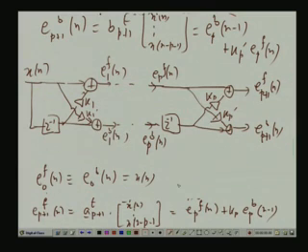This is called a lattice filter. This is one of the most celebrated things in statistical signal processing. This is used for AR modeling and particularly used in the speech context, because our speech generation mechanism in our vocal cord has been modeled as some kind of AR model which is driven by some white sequence.